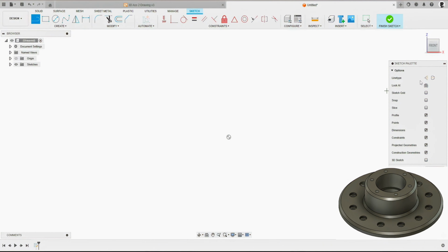So let's start off with the line tool then. I'm going to draw in our revolution line. Then make that, let's say 100 mil for now. I got a construction line. Good, move that dimension out of the way. Turn off construction line. Hit L on the keyboard again.